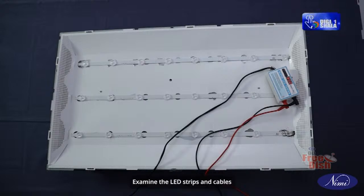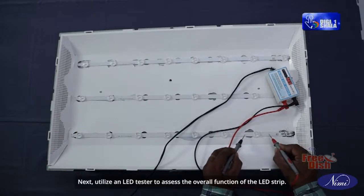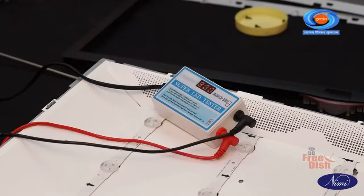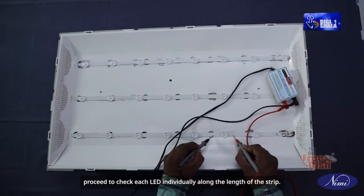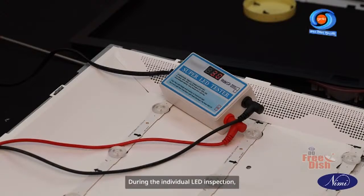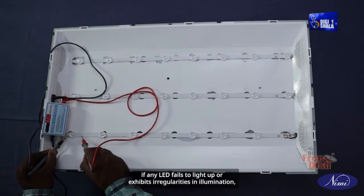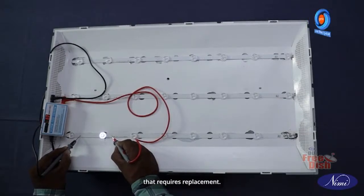Examine the LED strips and cables closely for any signs of damage, wear, or malfunction that may be affecting the TV's performance. Next, utilize an LED tester to assess the overall function of the LED strip. Following the overall function test, proceed to check each LED individually along the length of the strip. During the individual LED inspection, if any LED fails to light up or exhibits irregularities in illumination, it indicates a malfunctioning LED that requires replacement.